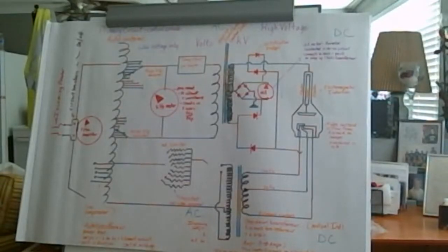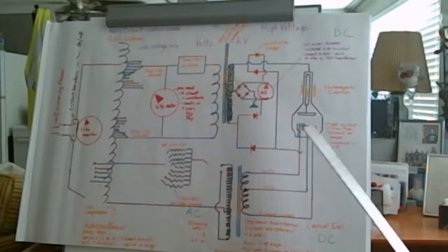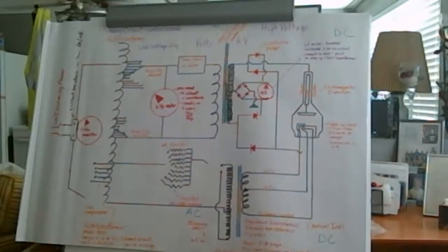Because if we try to get to the level of thermionic emission without having that filament sitting at a level where it's already warm, we would just crack the filament, okay? Because we're just talking about a little tiny thin wire, and it would just break the filament, and that would be it. And your $20,000 X-ray tube would be destroyed. So that'd be no good.